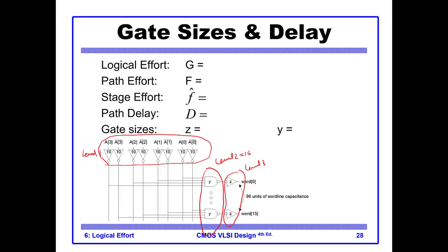So let's move forward with our design. That's why here we have level 1, level 2 and level 3. This is our 3 stages. But now, instead of the NOT gate, we insert our NAND gate, because this is what a decoder uses. So this can be one implementation of a decoder. You can implement a decoder with NAND gates, but you may also implement it with, for example, AND gates.